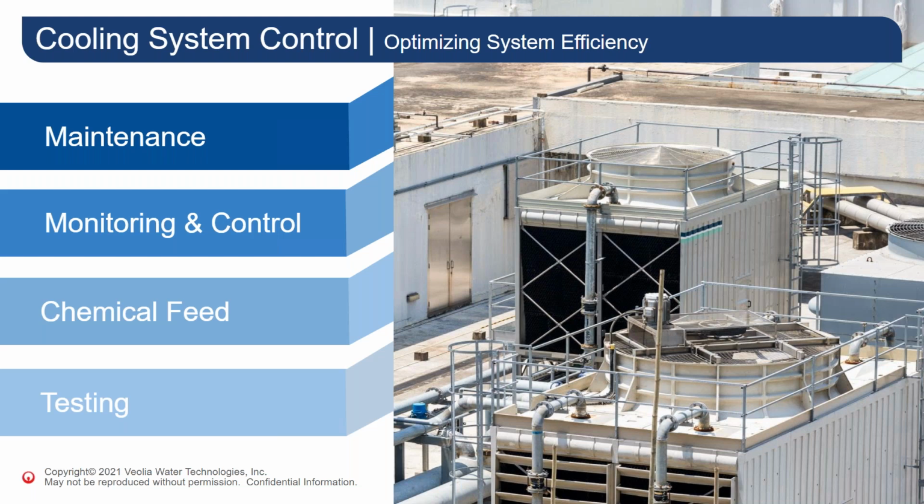Developing a chemical treatment program that addresses scaling, corrosion, and fouling is key to preventing problems that cannot be engineered out of the system. As we stated earlier, this treatment program must be developed specific for that individual site, taking into account its unique makeup water source, cooling system equipment it supports, system metallurgies, flow rates, temperatures, volumes, and heat loads when developing the correct chemical treatment program.